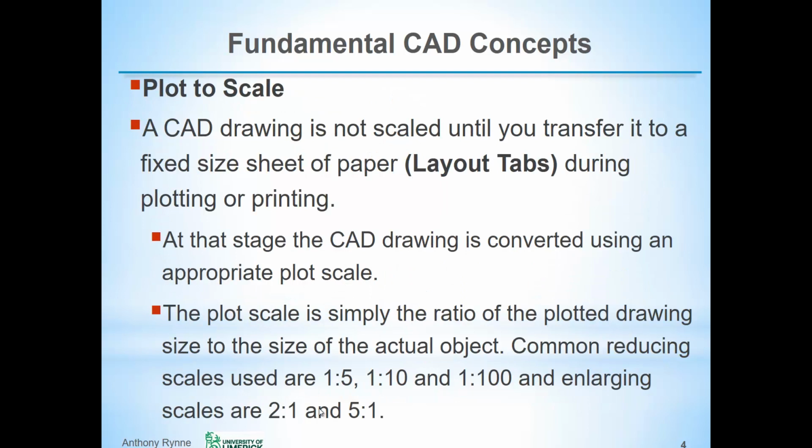Another important concept is that we plot to scale using the layout tabs after we've created our drawing. We simply select a layout which is associated with a particular printer or paper size, and then within what's called a viewport, you can set the appropriate scale to display your drawing. And we have reduction scales and enlargement scales, as you see there.